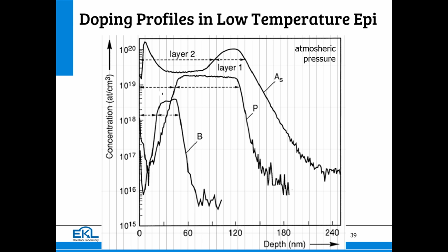And if that works so well, how do our dopants look in the same way? A doped silicon layer with an undoped capping layer on top. SIMS plot, here's the thickness, here's the concentration. And you see a very nice profile for boron. By the way, the slopes here are totally SIMS determined.